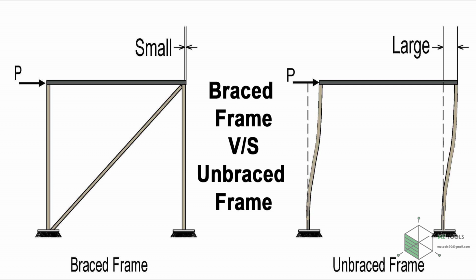Hello again. In this video we will compare both braced frame and unbraced frame, and we will see the effect of bracing. We will discuss three aspects: the stress, deflection, and the reaction forces. As you can see from this picture, when having a braced system under a lateral load, the deflection is small, but when having an unbraced system, deflection is higher.